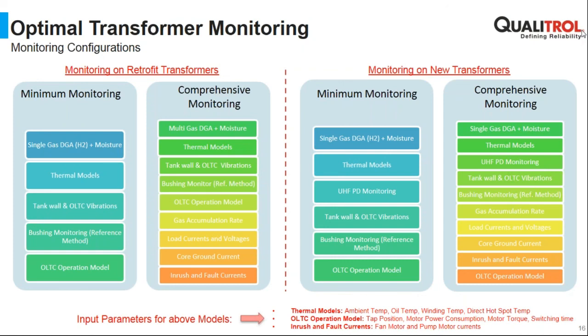Yeah, just adding on this, Thomas. Especially if you're talking about the wind farms, definitely wind farm transformers have a huge problem of transients. That's what we have got from our customers as well. And there, you should definitely go for transient monitoring, or in fact, power quality monitoring. So transient monitoring or power quality monitoring could be one of the good options for avoiding such kind of failures.